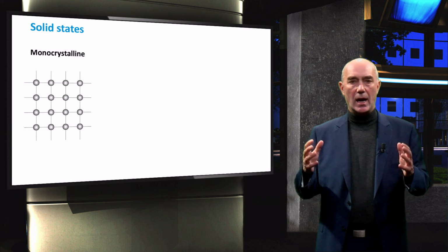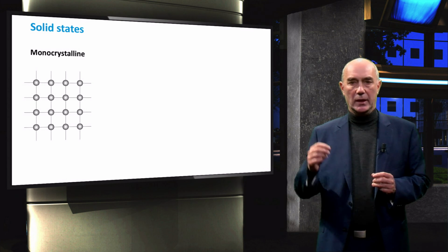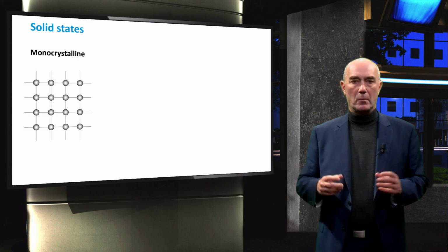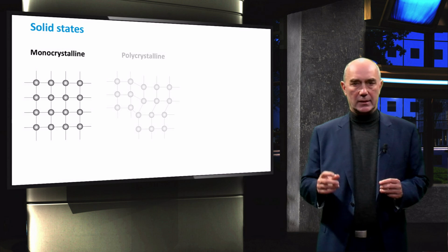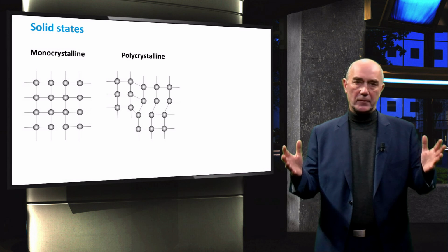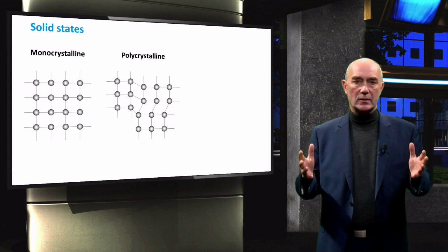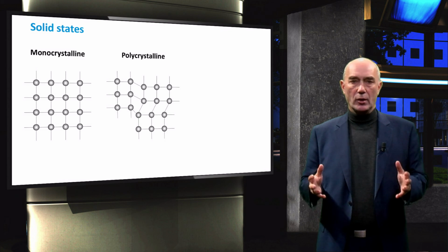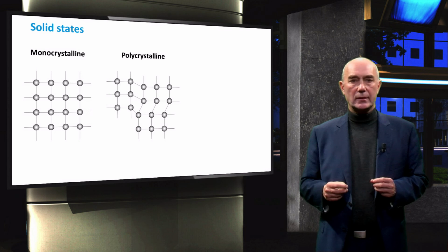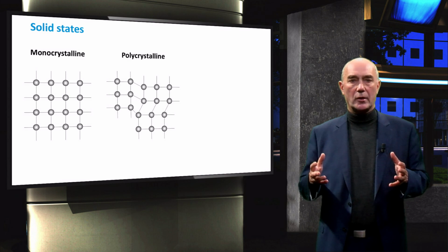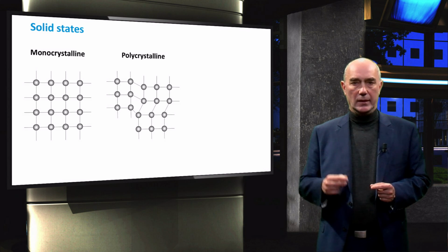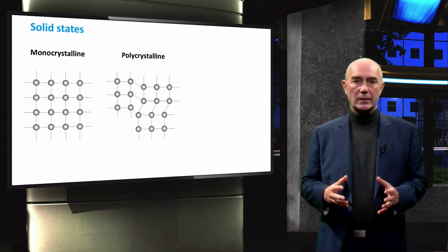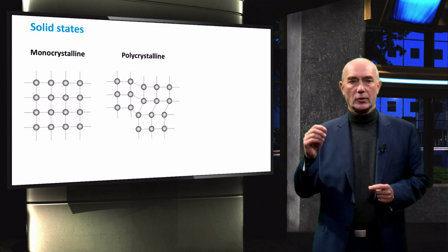Monocrystalline solids are highly organized structures where atoms form a continuous crystal lattice. However, in polycrystalline solids, regions of crystallinity are present with different sizes and orientations. These small crystals within the lattice are called grains or crystal domains. Nevertheless, the presence of grain boundaries makes the lattice non-homogeneous and not continuous.